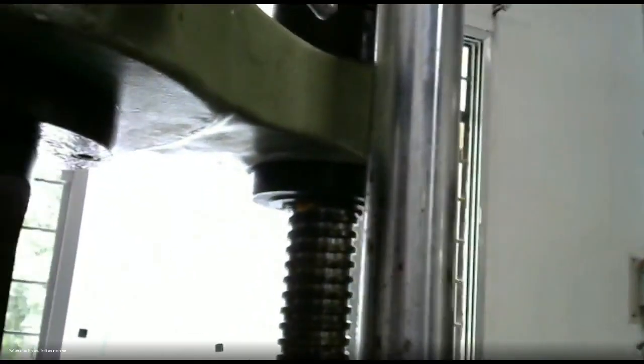And this is our movable crosshead, this is our bottom crosshead. And this is the wooden beam we have to set here, on these two different supports. First of all we have to measure the length and dimension of that beam. The beam is 750 mm, but the center to center distance of the supports is only 400 mm, and we require the additional length of beam here so that it cannot slip during the test.